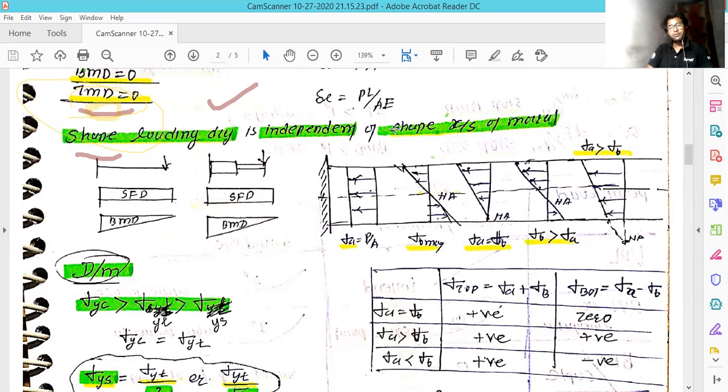But as we move from the second to the third case, in which the bending stress is higher than the axial stress, the neutral axis will remain in the cross section. Due to that, the topmost portion will be positive, but because the bending stress is higher, it will make the bottom section negative, which shows that if the top of that cross section is in tensile force, the bottom is in compressive force.